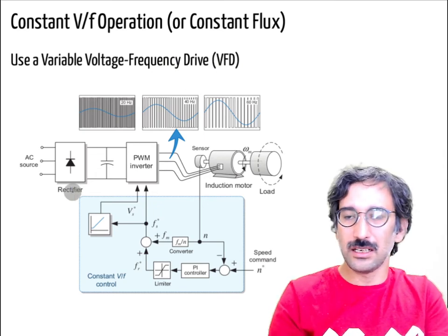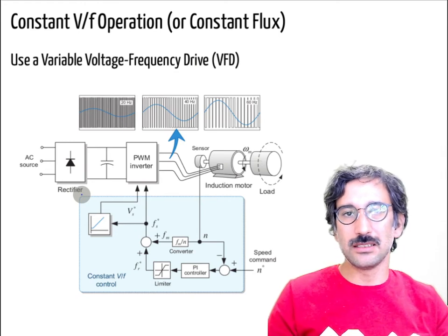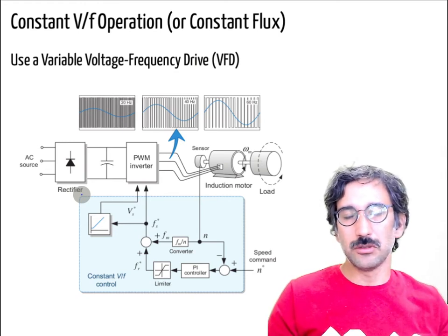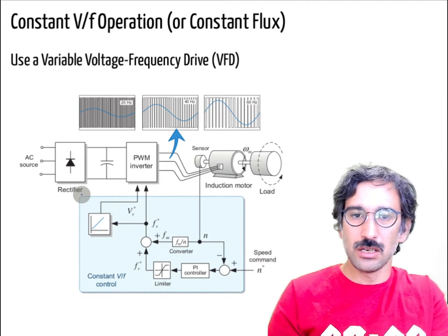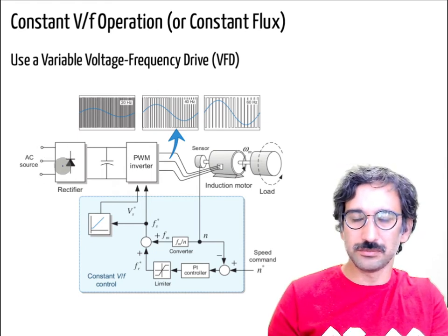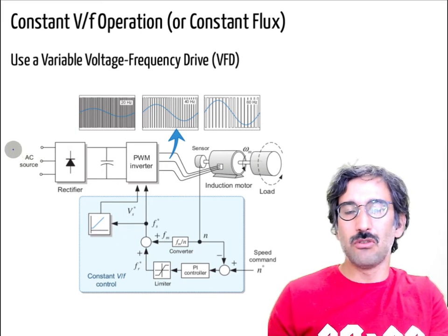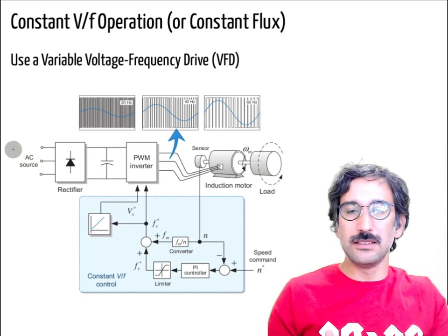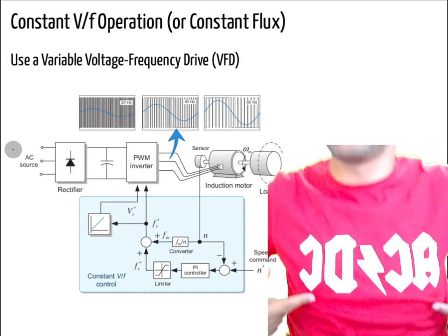Again, this is a topic for your fourth year classes in the power electronics course, and also the 462 utilization of electrical energy course. But the idea is, if it is a grid connected motor drive, you convert the 50 Hertz to DC, then from DC to AC.